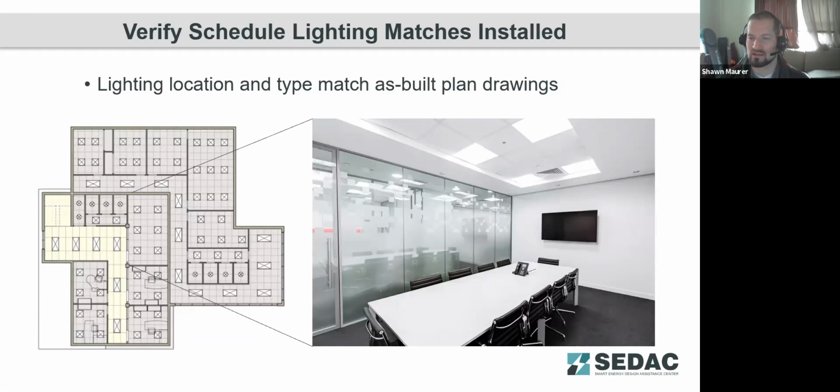They're also going to be checking on fixture performance as far as lighting output, lumens per watt, making sure that complies with requirements for the spaces. There are also now fixtures that have variable output and color temperature. As buildings advance in technology, we're doing different scene modes for different applications in a space.